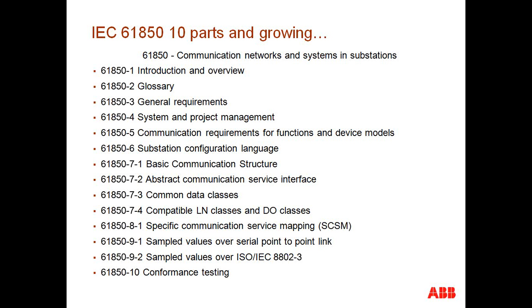Four key aspects, though. We're covering the specification or the performance requirements as to how the system should behave, as well as some suggestions, though, architecture-wise, as to how to implement the system. Number 2, 61850 is defining a data model, though, under which we could represent functions and pieces of equipment inside of the substation. Number 3, we're defining communication protocols, though, to exchange this information, which, as I mentioned, you really have 3: client-server, GOOSE, and sampled measured values.